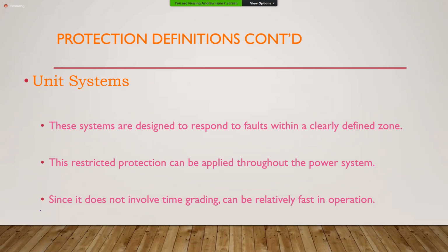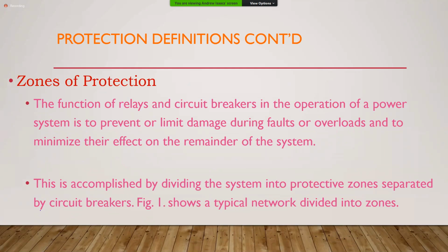If the difference is large enough, it operates. Right? That's the unit protection. And it can be applied anywhere. Okay? But the time graded, where it is looking at what's happening with A and seeing how long A is taking, then it decides the trip. That's your time graded.